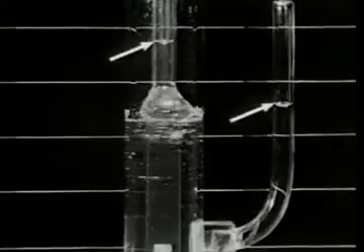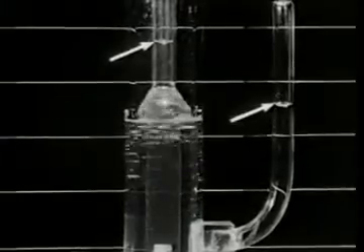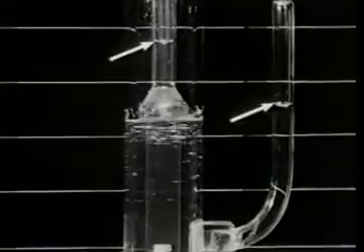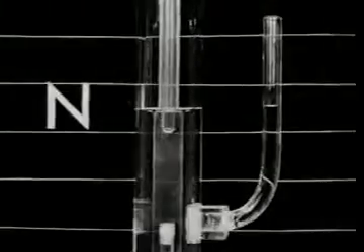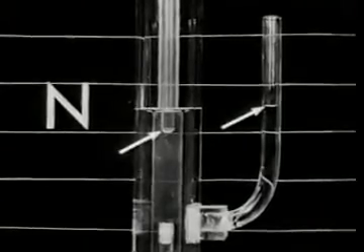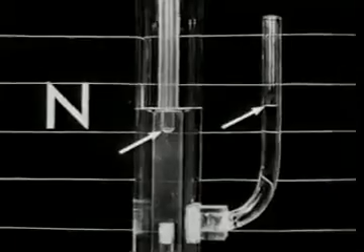Note that the stress exerted by the fluid normal to the cylinder walls is greater on the inner cylinder than on the outer. This is in contrast to the behavior of a Newtonian fluid, where the centrifugal field alone governs the pressure distribution.